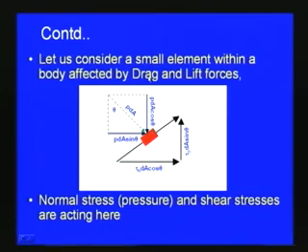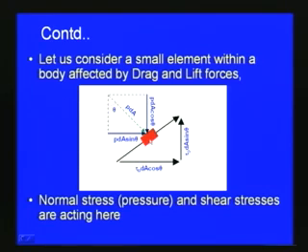Generally the drag and lift forces are mainly due to the pressure, that is the normal stress variation, and the shear stress acting on the surface. If we consider a small element within a body affected by drag and lift forces as shown in this slide, this is the body which we consider, and the pressure is P. If you consider an elemental area dA, the pressure force will be P dA, and with this angle theta, in this direction the pressure force will be P dA sin theta,